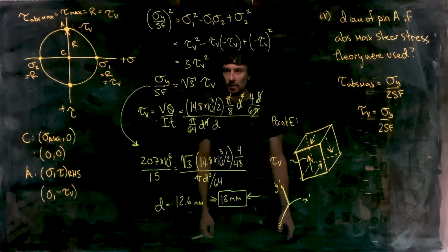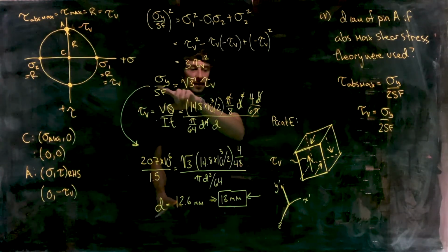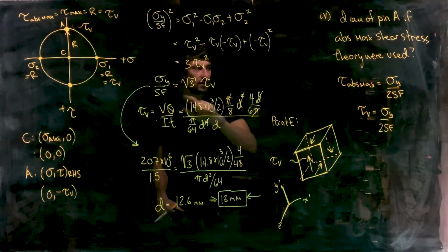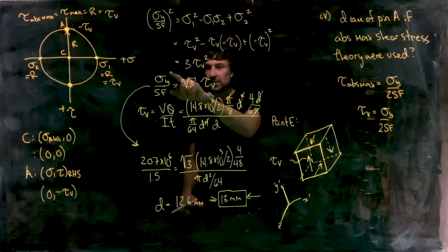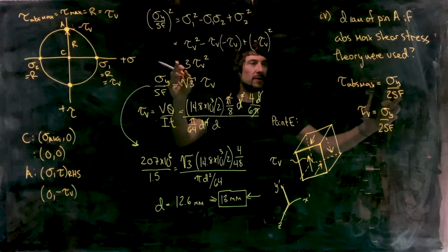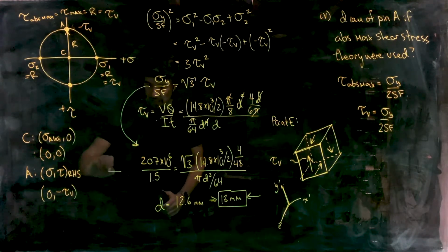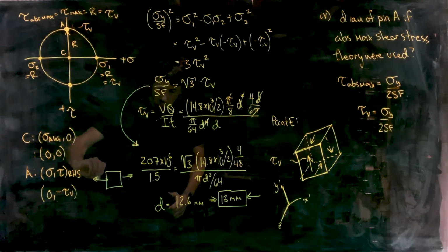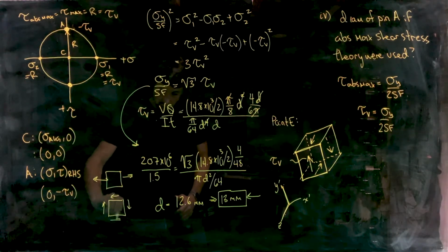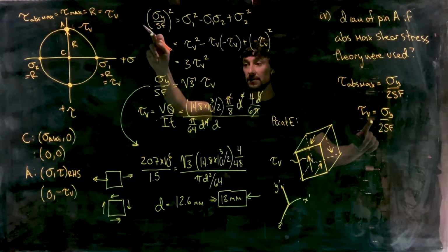Okay. So looking at the difference between these equations, here we've got sigma y divided by the safety factor. And if we move this over to the other side, 1 over root 3 sigma y divided by the safety factor, versus 1 over 2 instead of 1 over root 3, equals tau V. So even though both of these failure theories, maximum distortion energy and absolute maximum shear stress, were the same when we had a state of uniaxial normal stress, when we've got a state of shear stress like we do now, then these theories are a little bit different. They're going to give you slightly different answers.